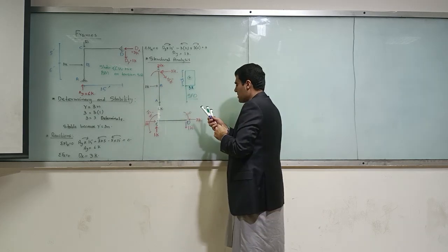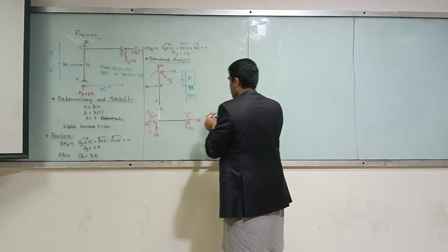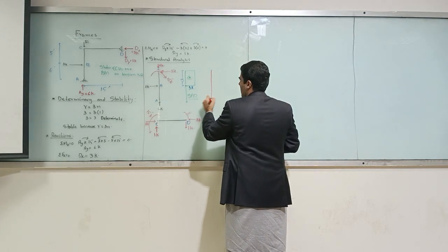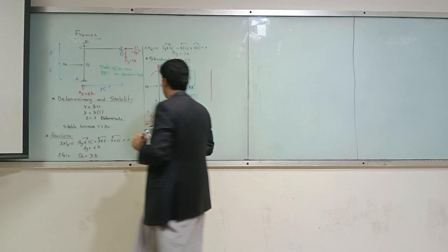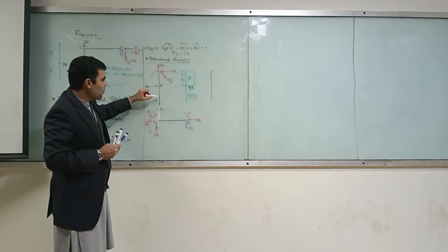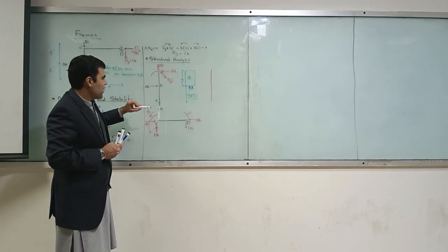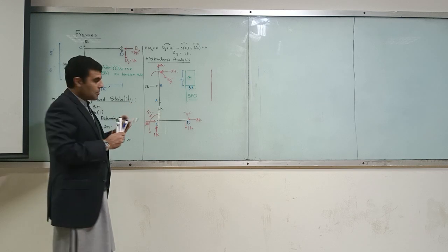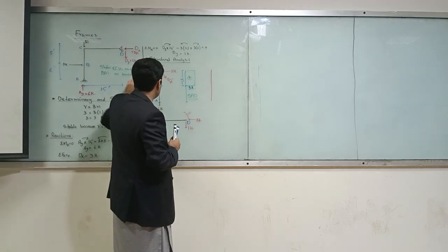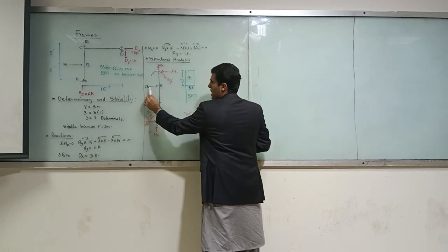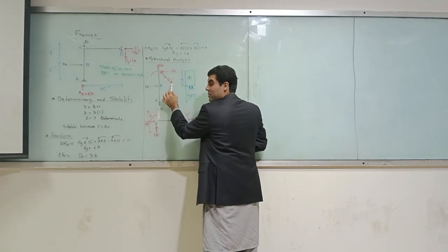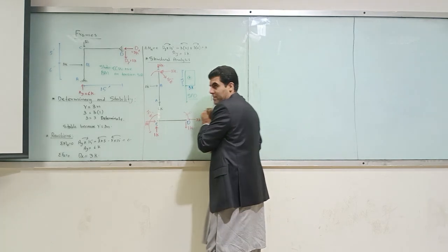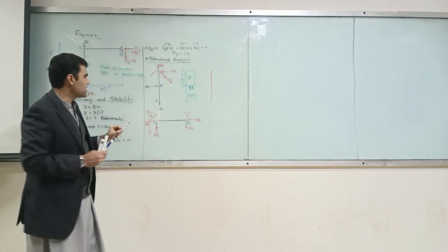Okay, now how about the bending moment? Which direction should I draw my bending moment in? You have got load applied in this direction, so tension will be in this direction. So I will draw it in this direction, not on this side.